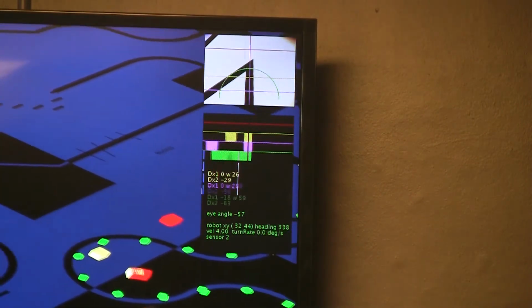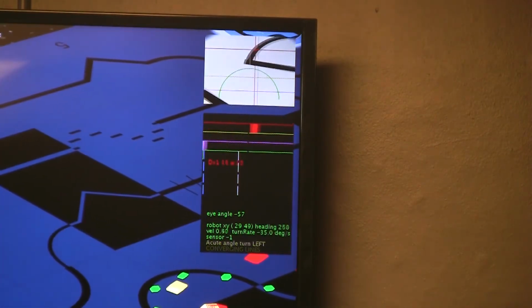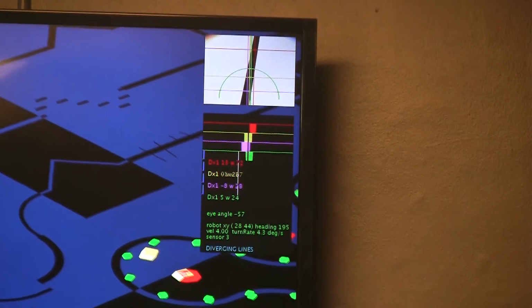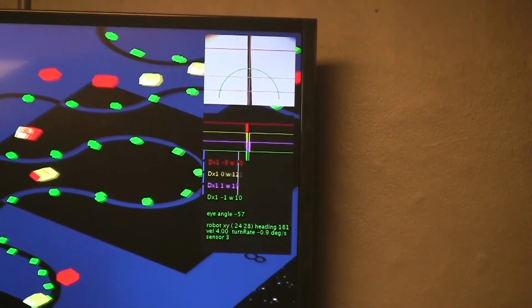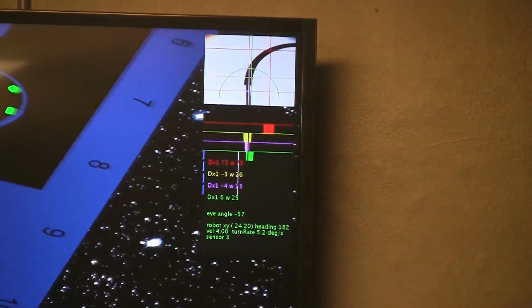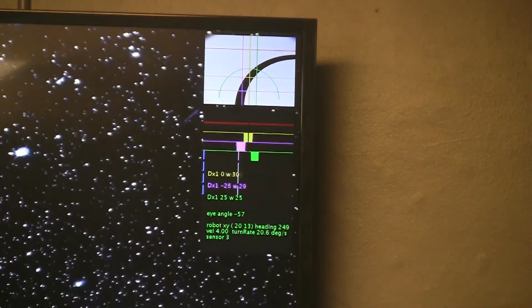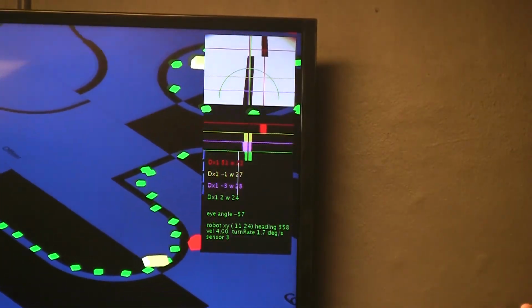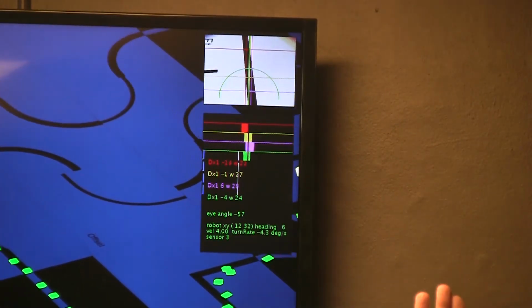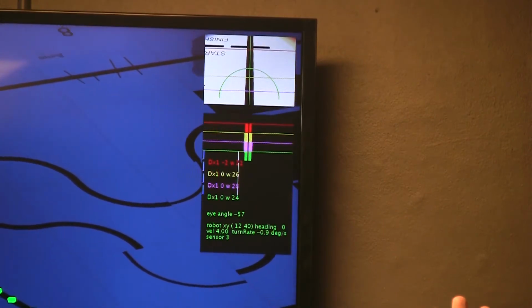What you're seeing is kind of hard to read, but I'm reporting a primary delta from the center line, or my heading. So I have how far the line is offset in pixels from the center, and perfect straight on, driving where I want to go, is 0.